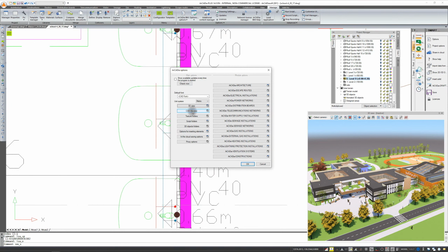There is also information about the 3D CAD view. The 3D CAD view, which I removed here from one of the projects. The first of these two settings is that my view here in CAD was switching from view to isometric view. If you don't want it to toggle, you can just turn off these two options. And if you don't want to have this 3D CAD view by default, you turn off this option. And I suggest that when it comes to installations or even architecture, I suggest turning them off at the beginning.